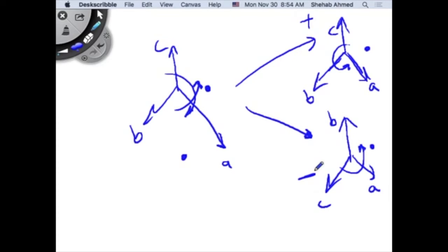What did Dr. Haytham say in the 338 course about flipping? This is what the symmetrical components theory says, right? It says that I can take this, chop it into a source that looks like this, and then do what? Take this and apply it to my three-phase equivalent circuit. This is balanced, right? So what can I do? Solve it using a single-phase equivalent circuit. Nice and simple, right? Same thing, I can take this and apply it to the same circuit. Nice balanced three-phase, use single-phase equivalent circuit.